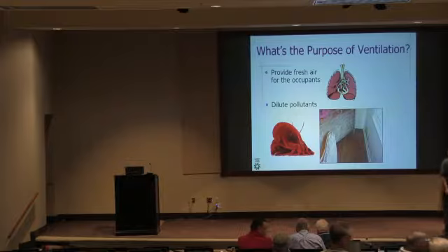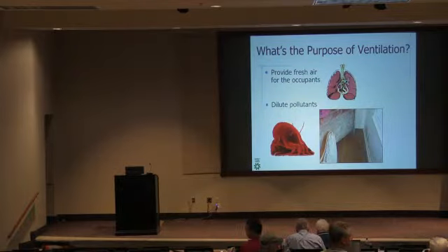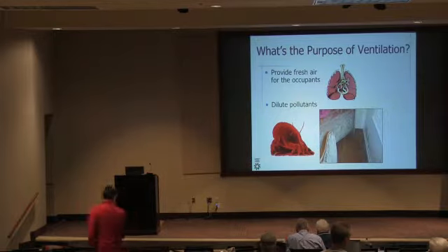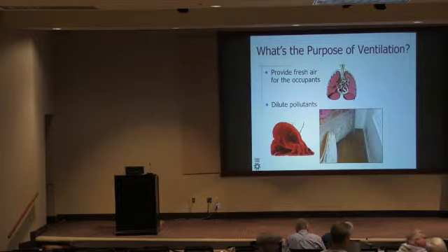Did you ever see, especially during the summertime, if you set your thermostat back, there's going to be less dehumidifying on the property. Your sheetrock is going to absorb a lot of that humidity, your furnishings, the rug. It's going to be more difficult for the system to dehumidify once it comes on. That's really not true. And the reason is, again, the dehumidification happens where? At the coil, as the air passes over the coil and is dehumidified.